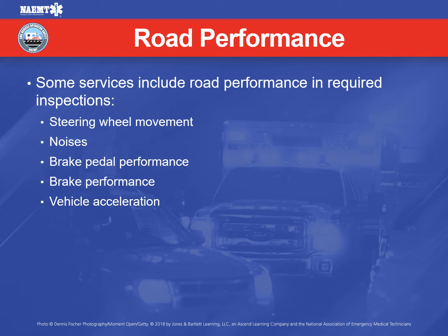Some services include road performance in required inspections. Is the steering wheel properly aligned and does it turn smoothly and accurately? Are there any unexpected noises? Is the brake pedal firm and does the vehicle slow per pedal pressure? Do brakes stop the vehicle evenly without pulling to either side? Does the vehicle accelerate with smooth engine operation and no skipping? Again, class, these items on the screen in front of you are inspected during an actual road test, where you take the vehicle out for a quick road test.